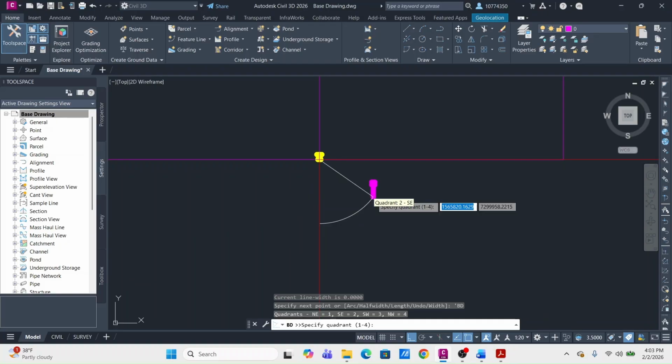So drawing this out, we're so lucky and fortunate enough that this legal description starts off straight onto a curve, and curves can be tricky. They can be really not fun to draw sometimes, but as long as you have the chord bearing and the chord distance, you can just draw that and ignore the arc length, delta, and radius for now, and you can circle back and do it later.